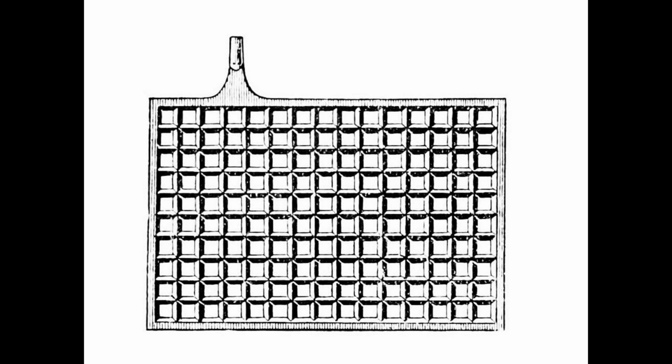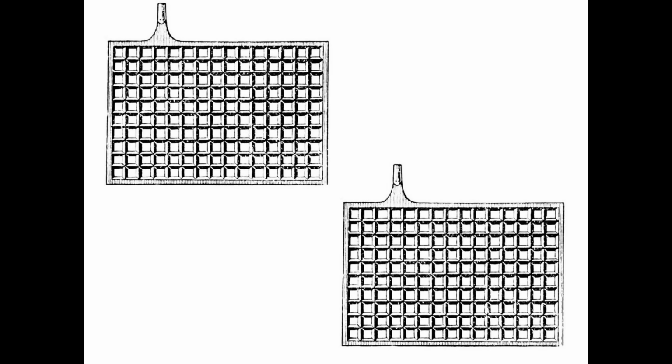So I'd like to take a moment and provide a quick recap of how a battery is constructed. What you see here in this example is a plate or a grid. Under both a positive and a negative plate exists a lead framework. Usually they add antimony or calcium to this framework to give it some strength. So in the top example, this would be my positive plate, and in the lower example, that would be my negative plate. As you can see, they are both identical right now.